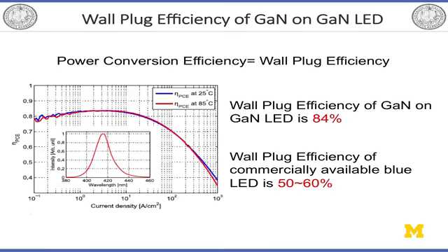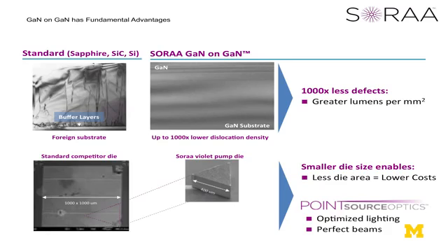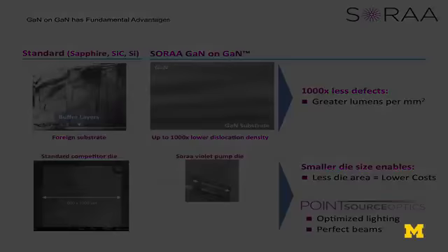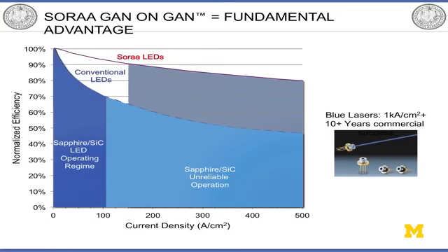So it is 20% higher. This is the comparison of the GaN-on-GaN LEDs with no crystal defects to the first generation, which has a lot of crystal defects because these LEDs are grown on sapphire substrate. And the chip shape is rectangular, but we use a triangular shape. The big advantage of these LEDs is that we can increase the current density.